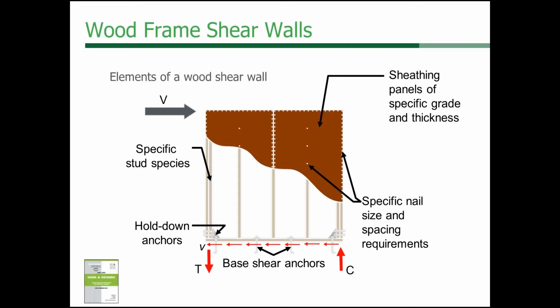The building did shake. It was tested without the finishes and then with the finishes, and they tested it to the 2,500-year event, a maximum credible earthquake, similar to what Buddy had mentioned previously on other tests. And what they found is that, in fact, yes, after it was tested, it did perform better, and in fact, it performed with improved performance, meaning that the drift limits were met, and the contribution of those finishes did help